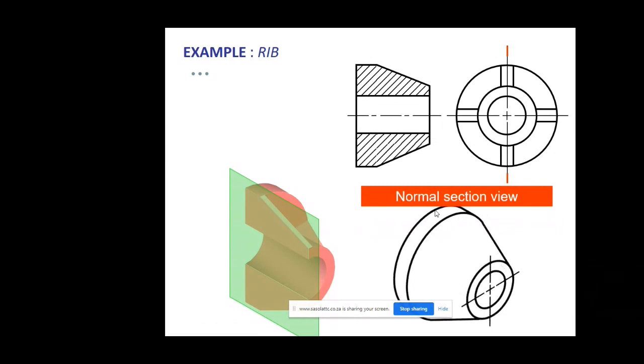We get all of these challenges from learners and students in quite a number of situations because of not having drawing models. But the essence of the matter is that they have now sectioned through a rib or a support as it is shown. And if they leave it like that, there's also a principal mistake, because the learners will have cut or sectioned through a solid line, which is one of the biggest principal errors one could commit. The final solution of a sectional front view is what is shown there.